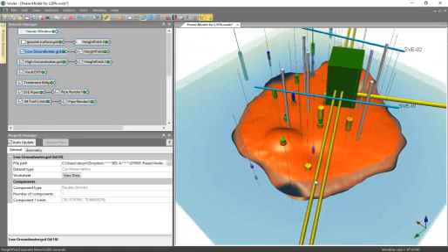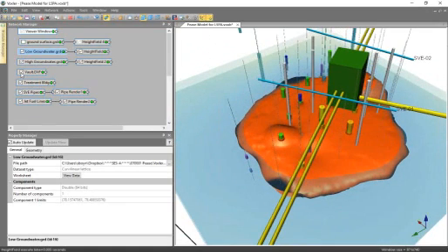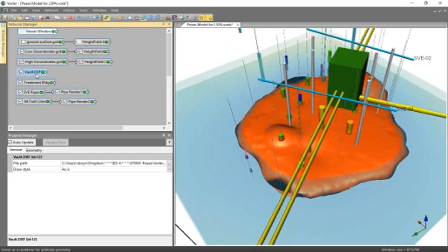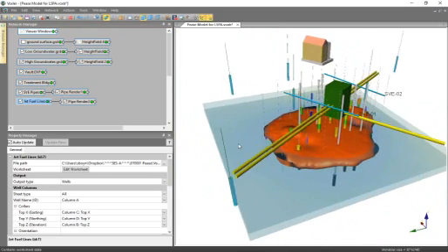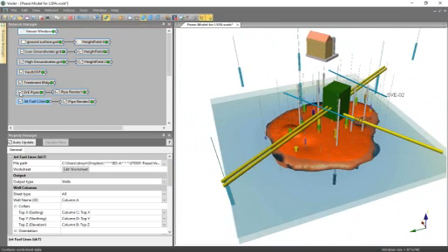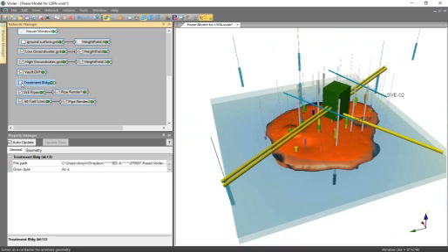As I zoom in just a little bit here, we also see the vault, and this was that 10 by 10 by 10 concrete vault where the LNAPL release in this project actually occurred. And then you can also see the jet fuel lines going in and out. These are the transmission lines. If I zoom out just a little bit more, we can also see the SVE pipes, or the venting pipes. And again, we also have that treatment building that Steve added to his model.